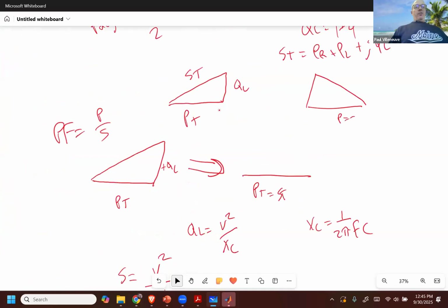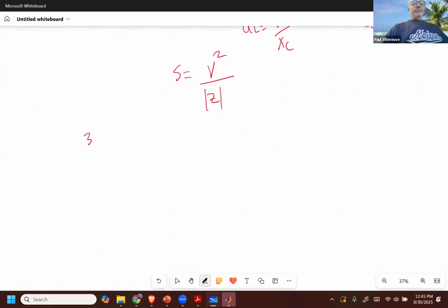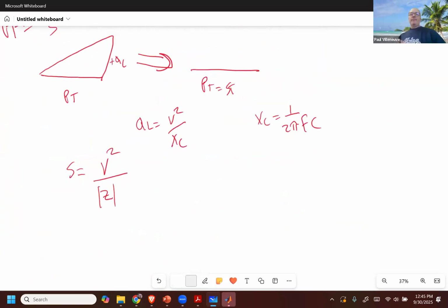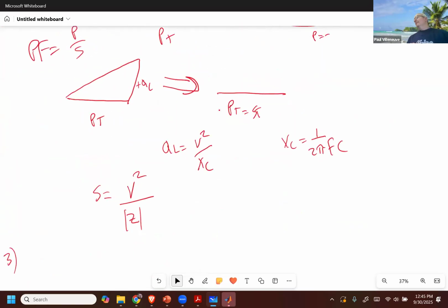Any questions on the first 2 problems? Yep, essentially taking the Q that we got in part A and just taking it to 0. Yeah, exactly, because it's unity power factor. Unity power factor means a power factor of 1. What happens when my power factor equals 1 to P and S? They're the same, right? So there's no Q term in there. So your capacitor has to completely cancel out the Q that's demanded for that load.